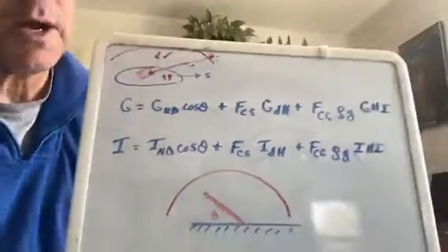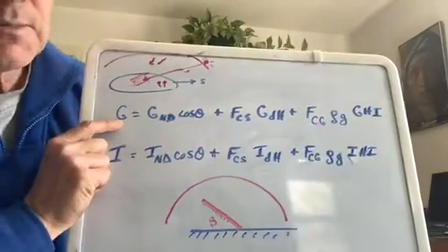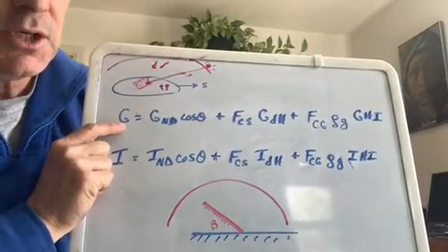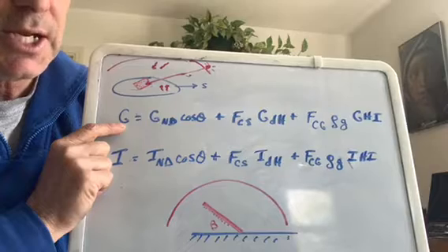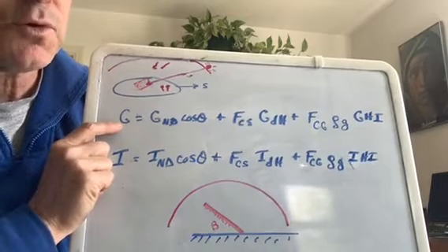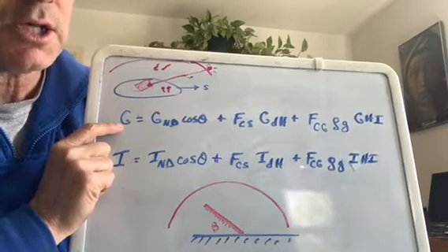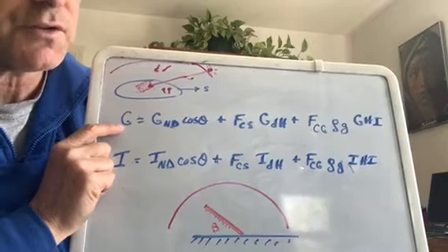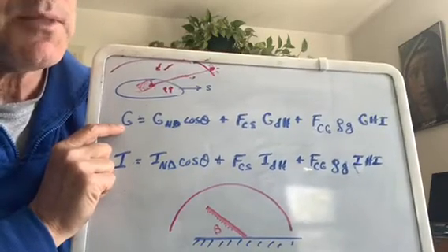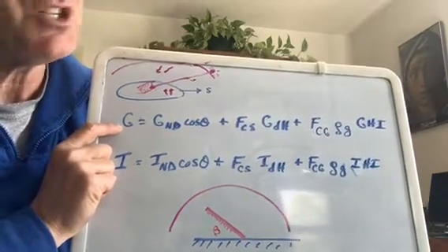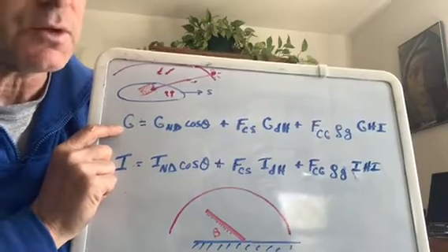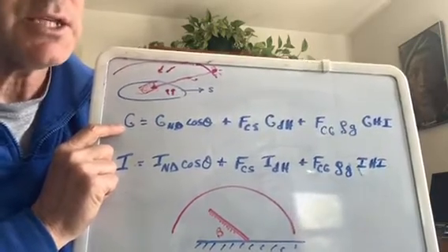All right, so hopefully you've gone over that. So these equations, sometimes I've done it as G sub T or G theta. This would stand for the total irradiation on a collector surface or on a surface like a window that could be tilted. So ordinarily we just call it G because it's not the horizontal, it's not the vertical, etc.